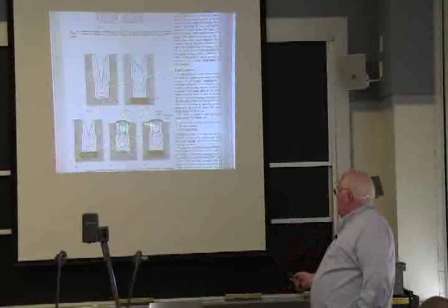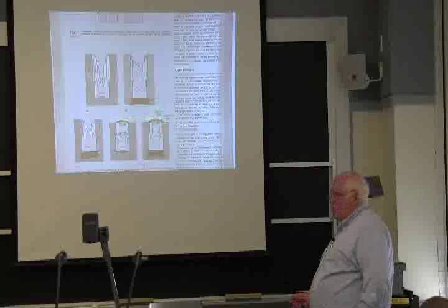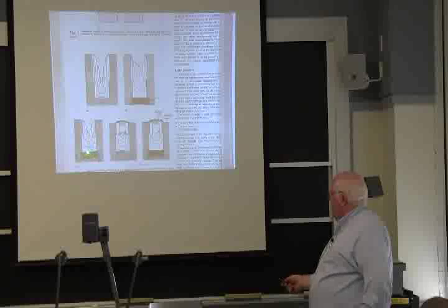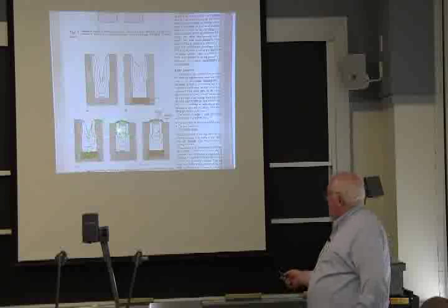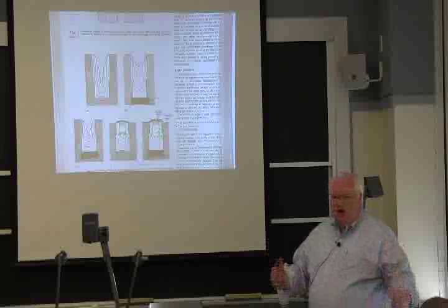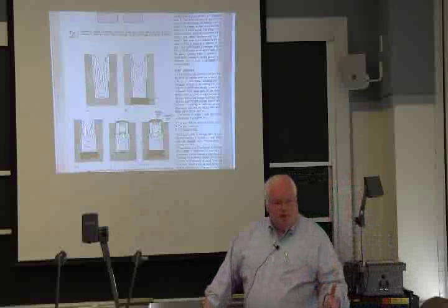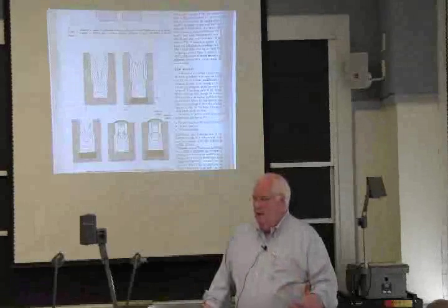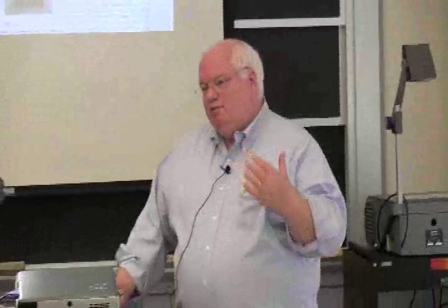So they also put in things like hot tops or radiation shields on the top so that you get a little bit more one-dimensional heat flow. Here you have a chill block with a shorter riser, but if you put a hot top on here, you actually can get a very small riser, and if you put a radiation shield up here, you can get things very flat. Anyway, you can change the cooling on these complex shapes by playing all kinds of games, and we do. But actually today, computers are fast enough that you can calculate these things.